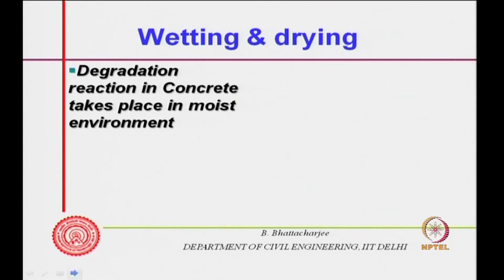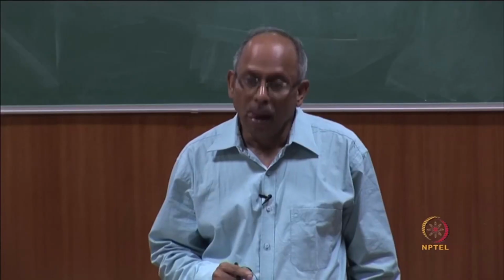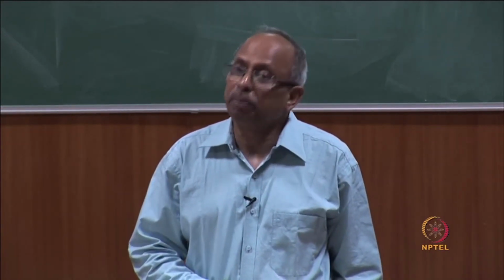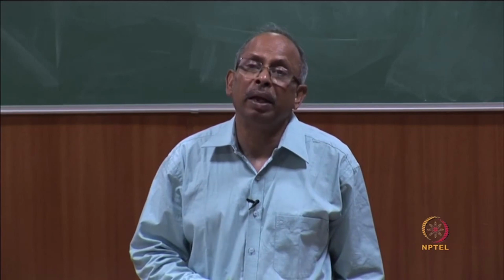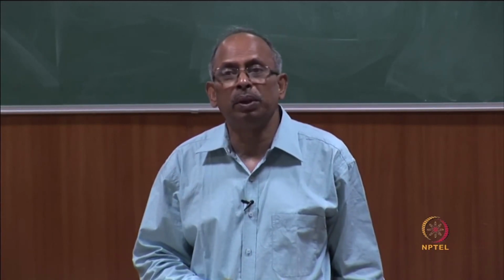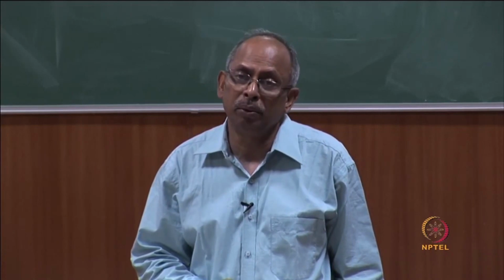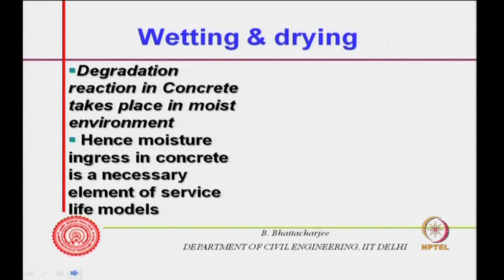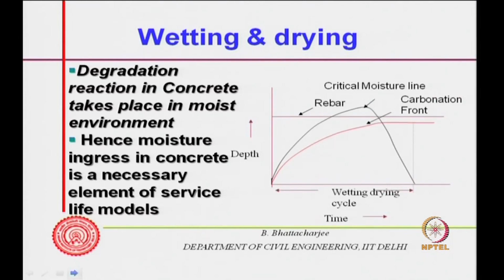Now, we already said the degradation reaction in concrete takes place in a moist environment, and concrete is not under fully saturated condition in tropical climate. Exposed concretes are subjected to wetting and drying. Even in western situations, colder climates, higher latitudes, it is actually under wetting and drying. Hence, moisture ingress of concrete is a necessary element in a service life model. So, all models must look into this wetting and drying, and if you look at it, for example, in our kind of climatic condition,